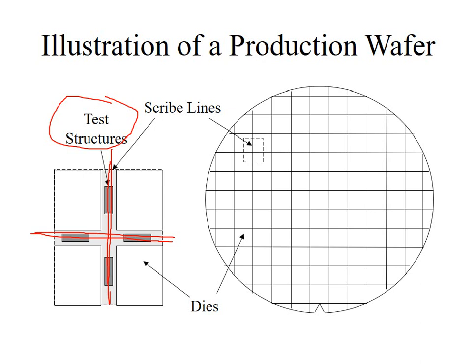Okay, we will stop this section here. For chapter 2, in the first part we discussed the concept of yield and the concept of the cost of a wafer. So you know what yield is: the yield is equal to the product of 3 yields: wafer yield, die yield, and packaging yield.